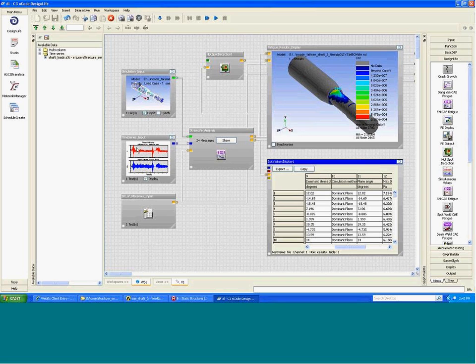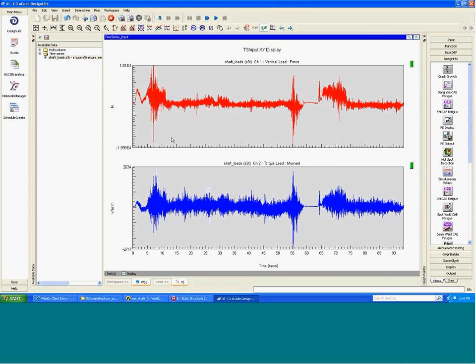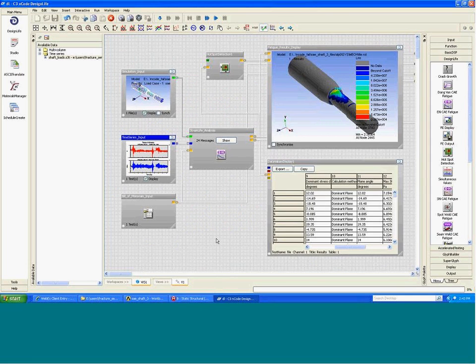For this particular case, this full cyclic definition that we show here represents one full cycle of time series load. So it's saying that if this is what happens during a particular event for the shaft, the fatigue life would end at 24,000. You would be at the point where that region in the notch would have reached its limit based on our analysis.